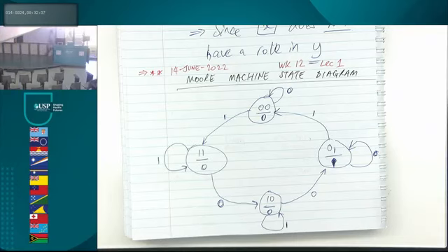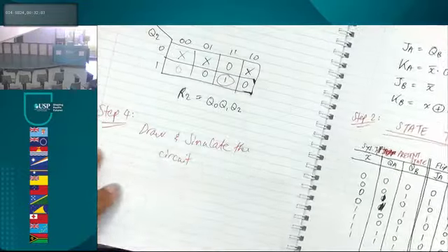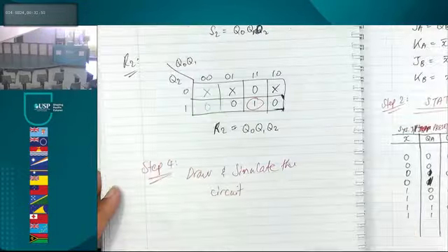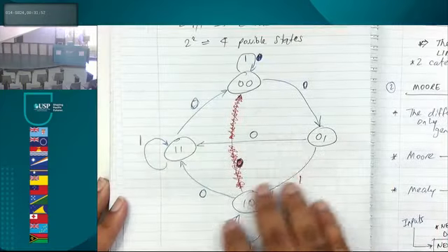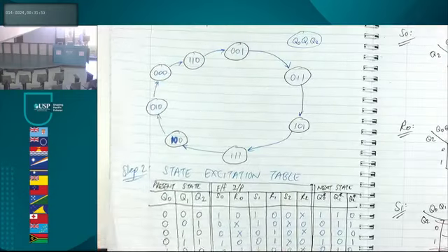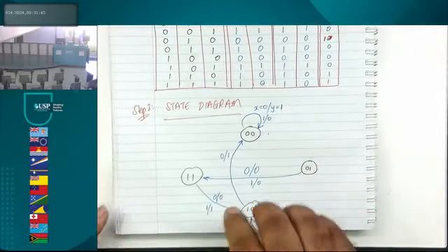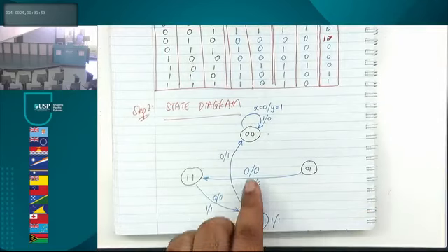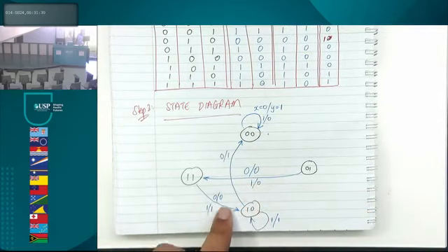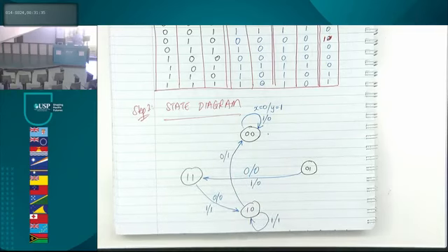And in the Mealy machine, it was very easy. In fact, the easiest scenario is when there is no output. No output, nothing to worry about. In this particular case, our output is shown along the transition lines. Can you see those transition lines? Input / output. So you don't need your bubbles to accommodate them.